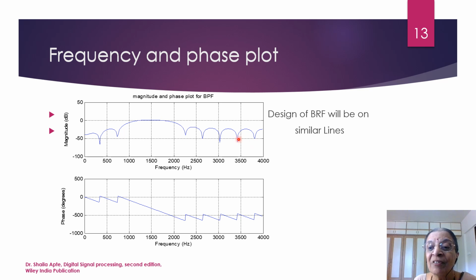These selected frequency points will then become the DFT coefficients, and then you take the inverse DFT to get the filter design. So in this case, we don't have to truncate it and then make it causal. Those things will not be required, because considering the actual response, we try to fix up or select the frequency points. So we'll consider this frequency sampling method in detail in the next video.